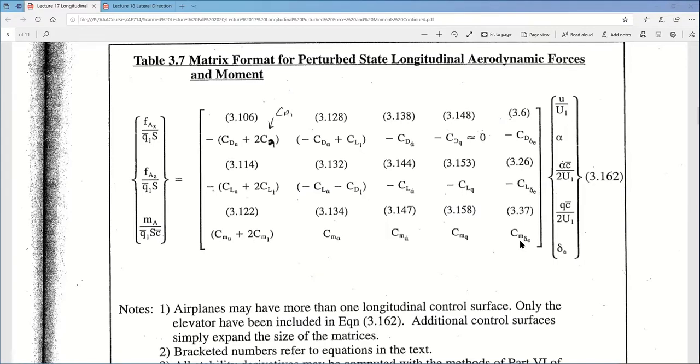So going through the formal procedure we've been doing, again, we don't want to do the derivative of this with respect to the elevator, and we're talking about a perturbation. So the elevator is already trimmed at like -2 degrees. Then we're going to go just a little like -2.1 as perturbation.